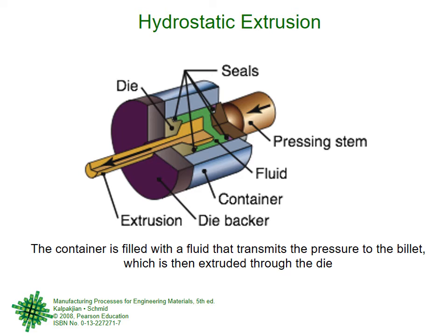Okay. Now holding the liquid, the lubricant now requires some seals, right? So seals have to be here, seals have to be here, seals have to be here. So it will complicate the setup by having certain seals and so on. But if you can have that, then you can do the whole process at a much lower load because you are now bypassing the friction force.